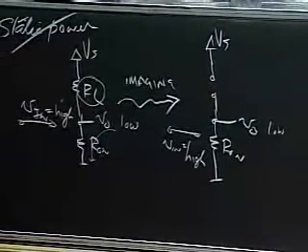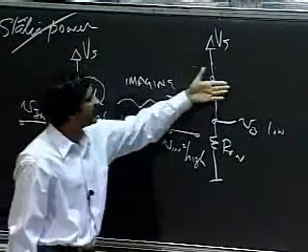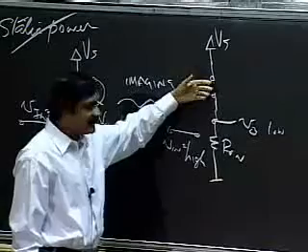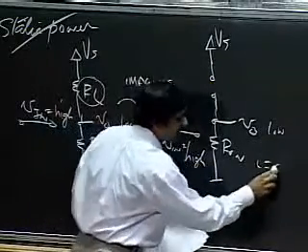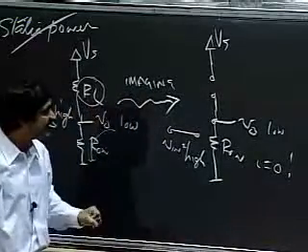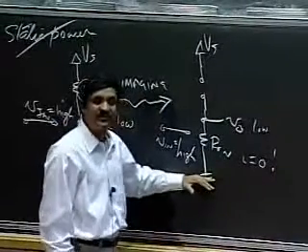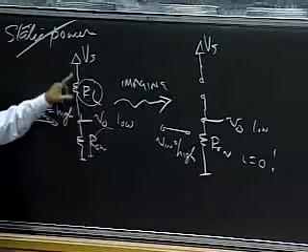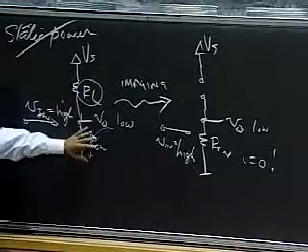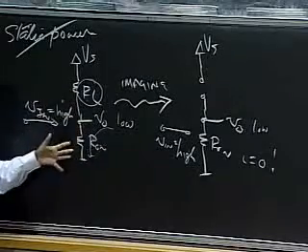I get many benefits by doing this. One benefit is that I've opened the switch here, so I don't have any standby current. The standby current is 0. Second benefit is that my output gets dragged down to ground. Out here my output was Vs multiplied by R on divided by the sum of these two.